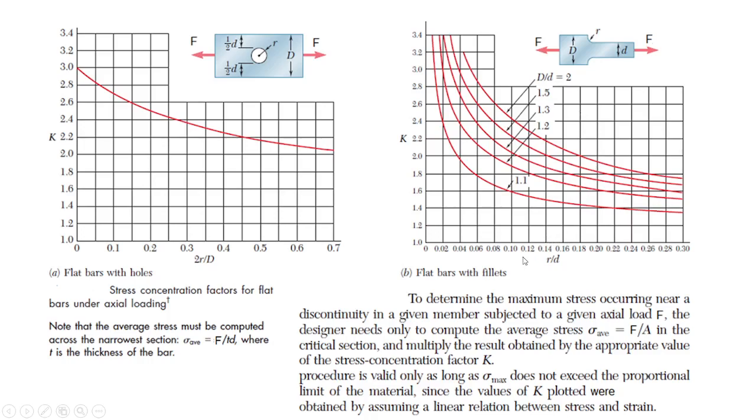Beforehand we used these graphs, but today, in a CAD environment, we can determine the stress values using the tools of the software. Since the risky part is at the place where we have a discontinuity or abrupt geometrical change, we need to determine the stress value more accurately in the vicinity of such risky places.